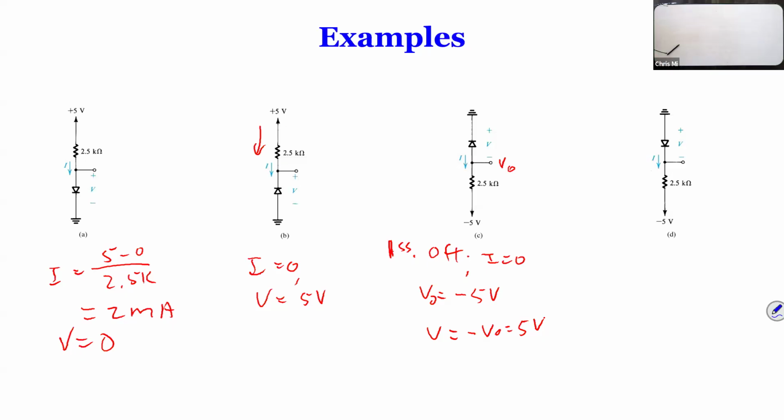So I thought you said that a negative voltage is what we wanted. No, depending on how you mark it. Well, in this case, they mark the ground as positive. They mark the other side as positive. This side is negative. So the line is the negative side of the diode? Well, okay, the easiest way to understand it is that you want the arrow of current to point the same way as the triangle of the diode.